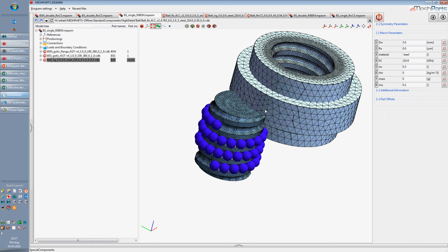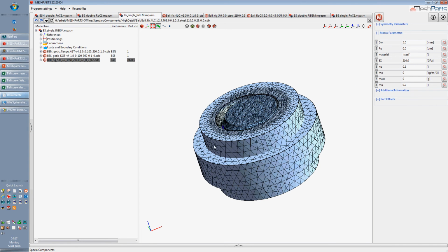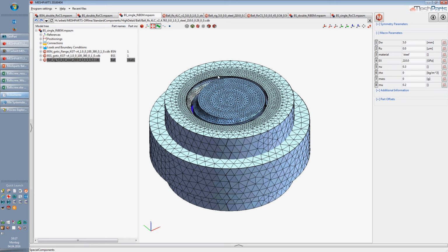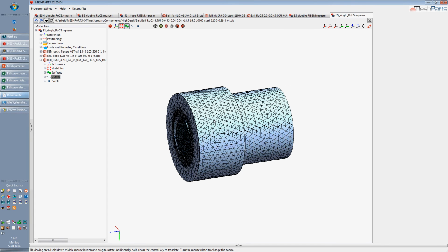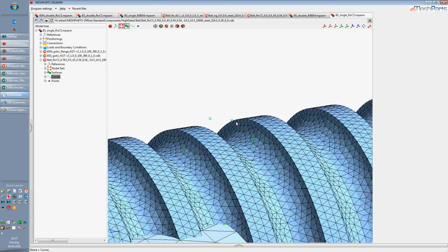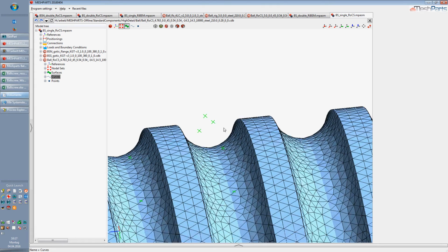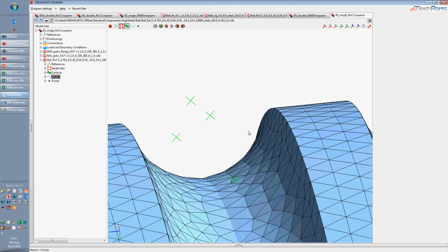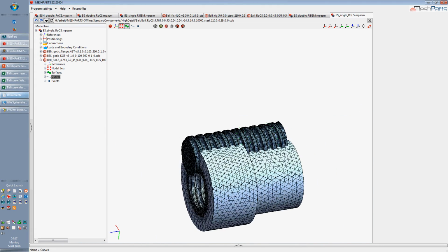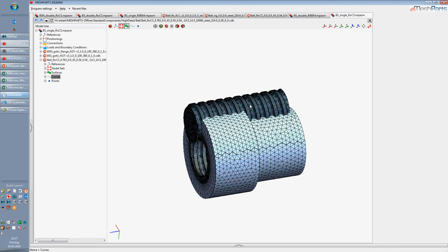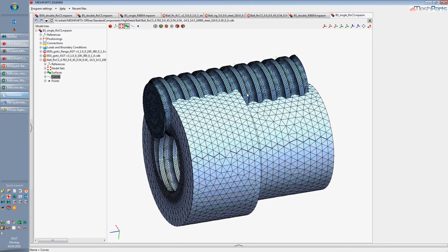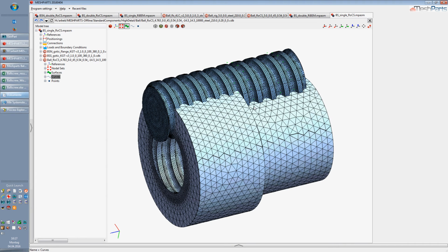There is also another predefined assembly for the ball screw that contains the ROX models. You can see it here. Like I said, the ROX models consist of nonlinear springs, so there is no 3D geometry describing the balls. We have only those nonlinear springs here, which are still very near in accuracy to the 3D balls, and have the advantage that the simulation time is extremely short.